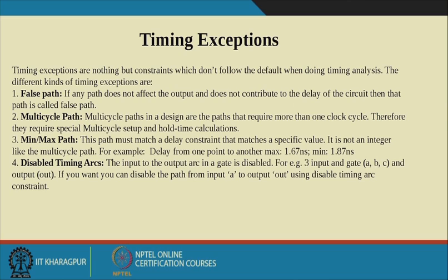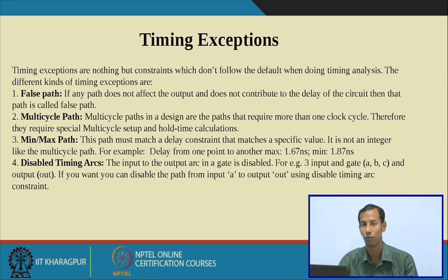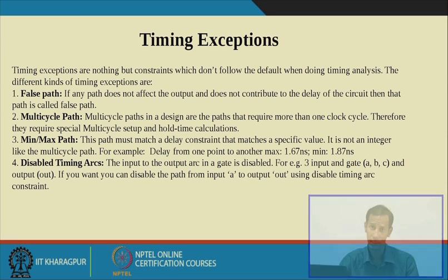I can disable the timing path from A to the output, so that it will not come into the picture while calculating the timing information for that particular gate. For a bigger circuit, I can disable one path so that it cannot affect the whole timing requirement of the circuit.